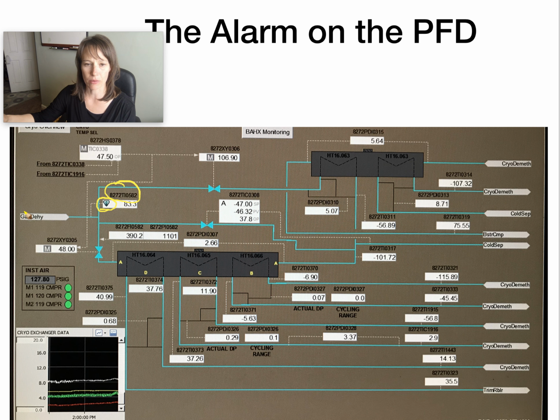So taking this information together, both screens would give you as an operator some indication of the problem that's occurring and where it's at. We can see the flow lines here coming in from the gas dehy and then going this direction through the valves, and so we can see that for some reason it was coming through and the temperature here increased. Now we previously decided because this dropped back down that it may be an issue with the transmitter. If it was still climbing, we may have an issue with the gas leaving the dehydration unit that's causing the gas to be too hot.